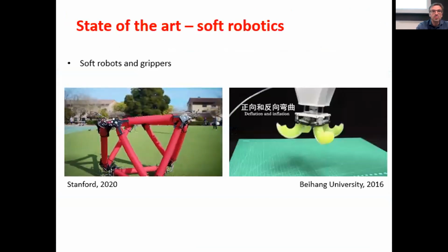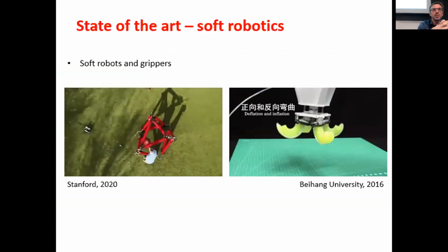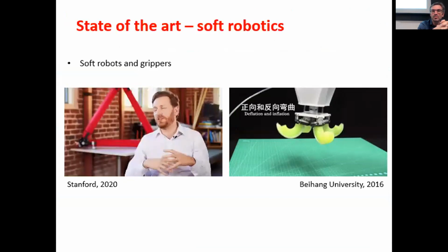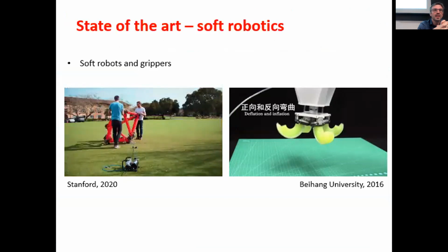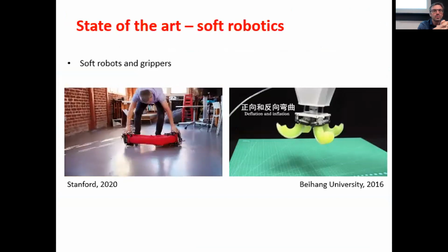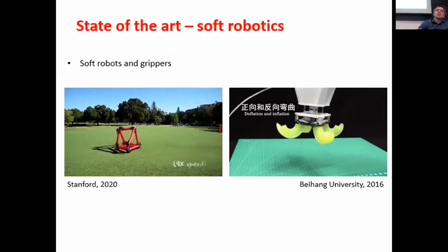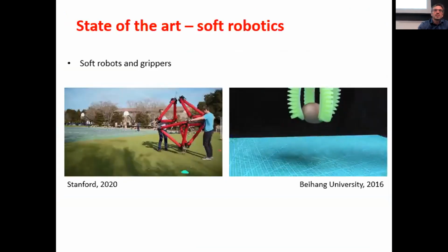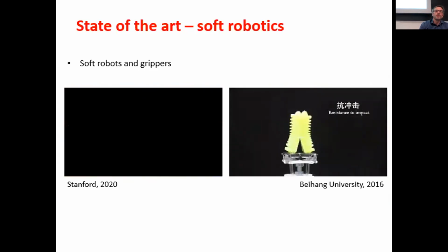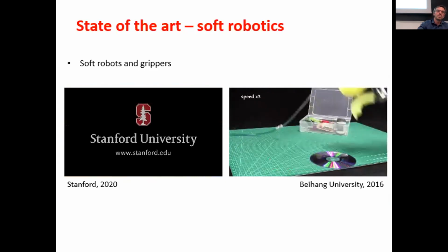And finally, some people work on soft robots. We will only deal with rigid robots, rigid bodies, but soft robots are introduced because they are compliant, but they have nonlinear dynamics, are more difficult to model, more difficult to control, and of course more difficult to make accurate, because you cannot control position really nicely. But you can see here a gripper. This is a way to grasp, I don't know, fruit in agricultural applications. You grasp objects with this compliant gripper.